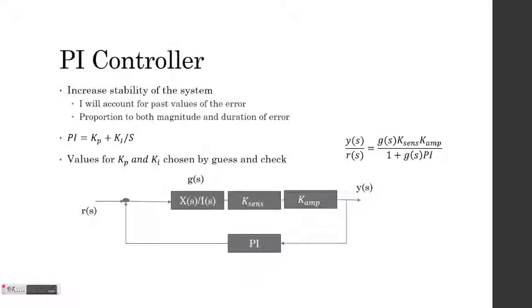The PI controller is a combination of proportional and integral. The contribution from the integral term is proportional to both the magnitude of the error and the duration of the error. The I value will account for past values in error. The integral term accelerates the movement in the process towards the set point and eliminates the residual steady-state error that occurs with a pure proportional controller.